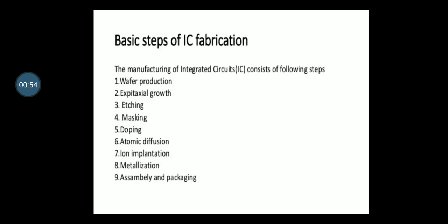The basic structure of an integrated circuit consists of four distinct layers of material. First layer is p-type silicon substrate upon which the integrated circuit is to be built. The second layer is thin n-type material which is grown as a single crystal extension of the substrate. Third layer is silicon dioxide. It provides protection of the semiconductor surface against contamination, and also the selective diffusion of impurities is accomplished by the SiO2 layer. Fourth layer is aluminum layer to supply necessary interconnection between components.